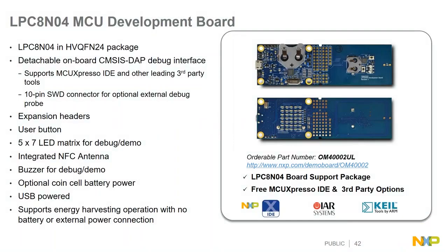So first of all, we have an LPC804 MCU development board. It's a low-cost demo board where you can start your prototype. We have the LPC804 HVQFN package available here. We also have a detachable debug interface on the left side of the board. We also have a 10-pin SWD connector for optional external debug, so plenty of debug interfaces. We also have expansion headers, and a 5x7 LED matrix for debug and demo.